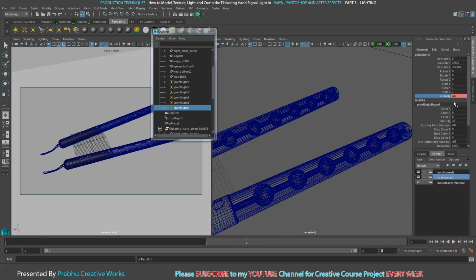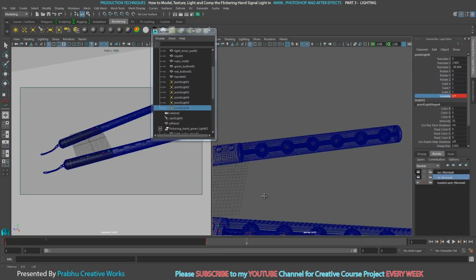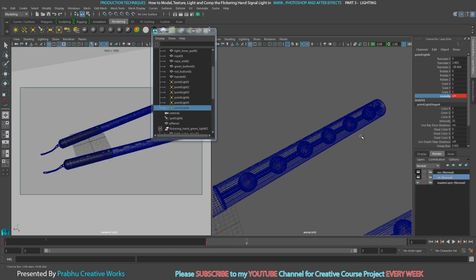Now I want to set this visibility off. So select this one, press 0 and press enter, and then right click and choose key selected. So that means, see over here, in the first frame it's on, in the second frame it's off. So you want to do all the other lights also.